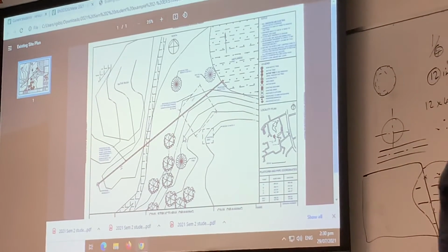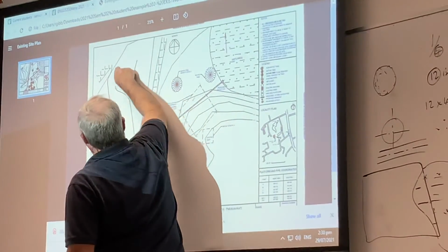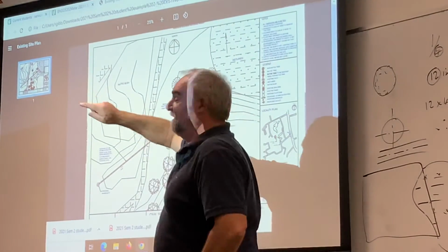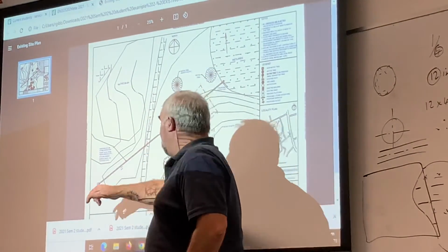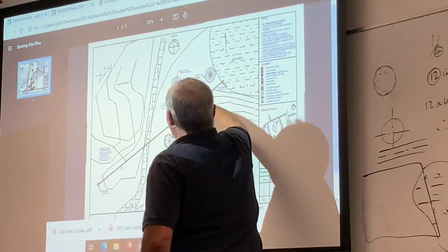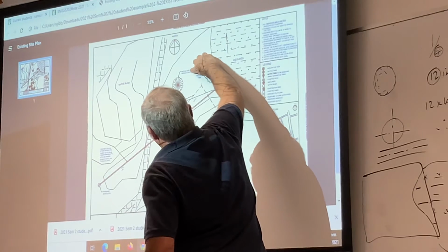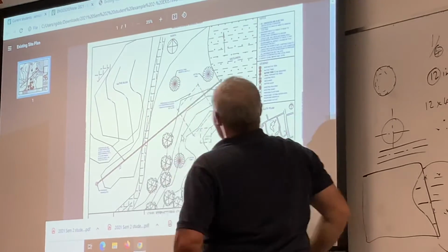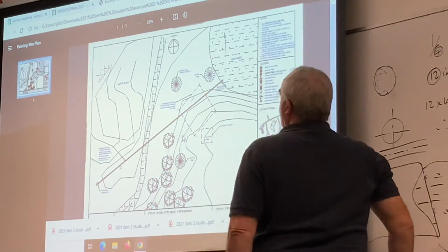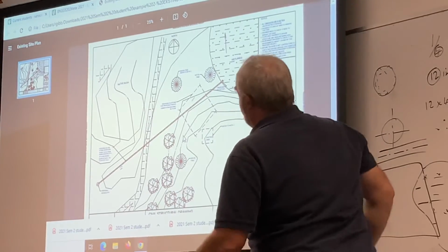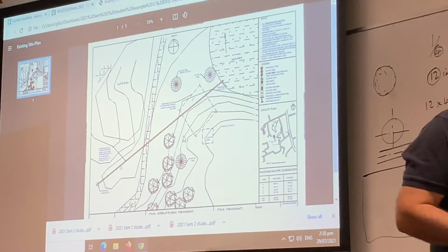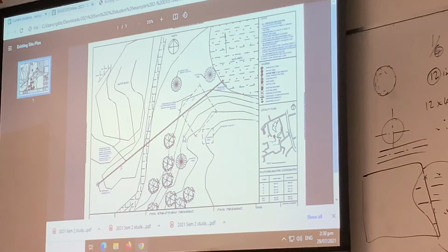Other things with this, that's how they've shown the bush. Just with a straight line, so they missed the mark there. At least they didn't have the grass on there. What would Ingrid do to you if you started your text on the top pointing down? You've got to put the text from the bottom line, don't you? On the bottom left or right, depending on which way the arrow's going to be. So if you want a good kick in the bum, you're going to get one from me if you start doing that in this class, because you're supposed to know those things from technical literacy.